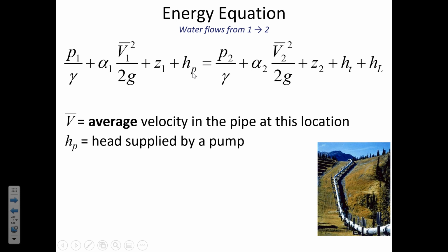That's a water tank. So if this is 1 and this is 2, then that pump would not be included in the energy equation. But if the pump is between 1 and 2, then that is when you would include the energy that's being added by the pump in terms of head, then it would go into the energy equation.